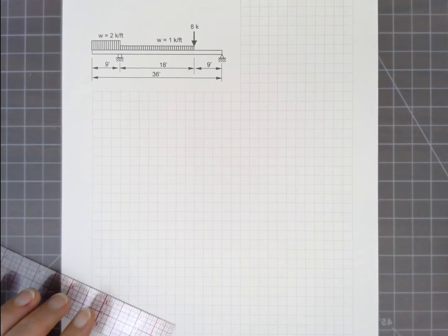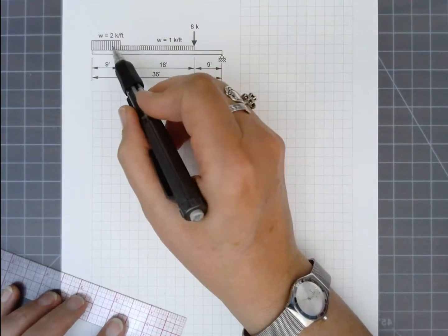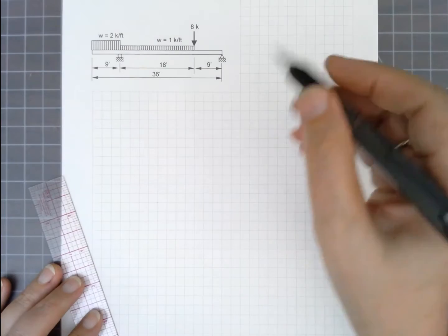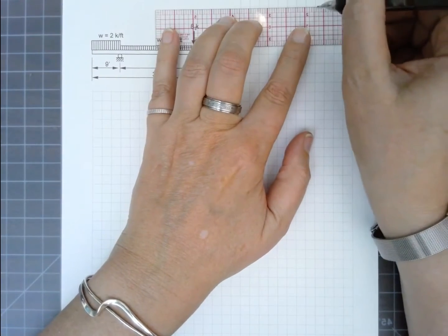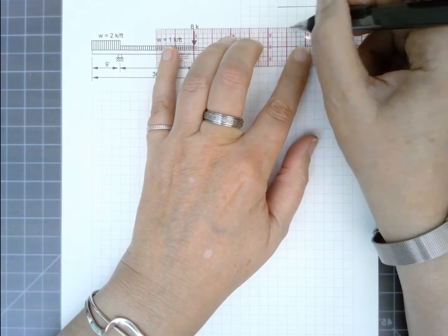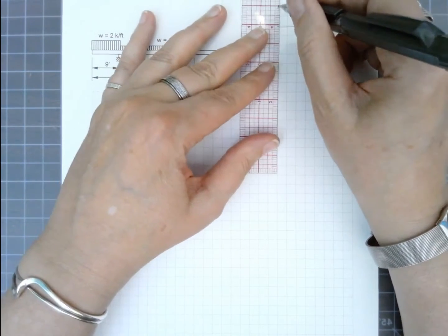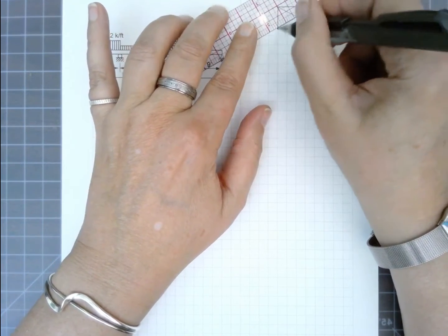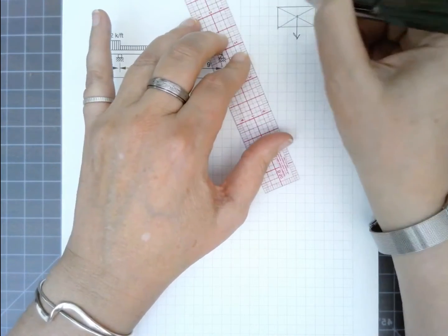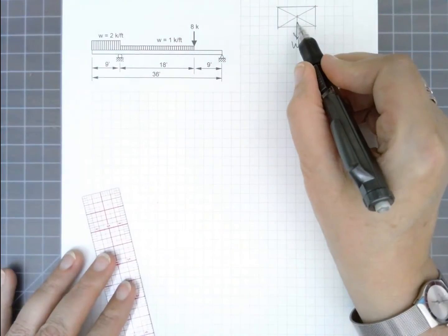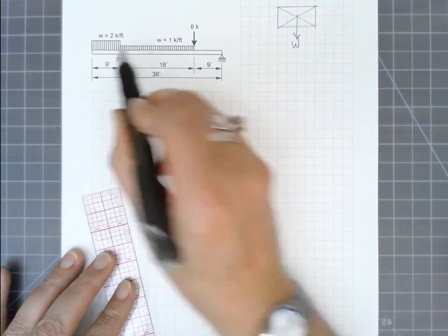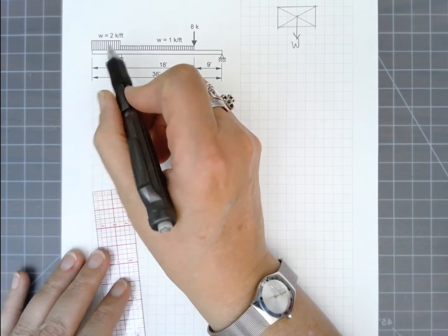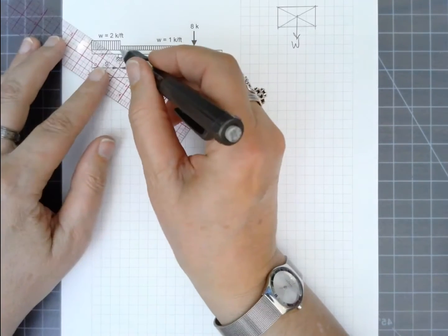So the first thing we need to do is to understand how these distributed loads act essentially as concentrated loads. Anytime you think about a rectangle that has a center of gravity, it's always going to act through the middle of that object. So this is essentially what's happening. If this is our total weight, the balance point is through the center. So all of these distributed loads behave in the same manner. The equivalent total load acts through the center of gravity of each of these portions.